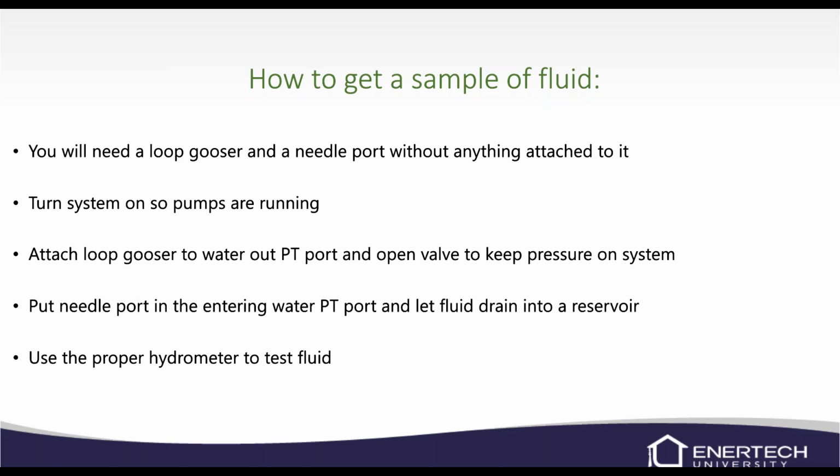If you ever have a problem with a closed loop, water quality issues, and you need to get a sample of your fluid, or if you need to check antifreeze levels or something like that, on a pressurized closed loop, it's a little bit more difficult. On a non-pressurized closed loop system, it's pretty easy. On the non-pressurized, there's a cap right on top of the flow center, and you can just take that cap off and dip some fluid out of there. On a pressurized system, it's a lot harder.